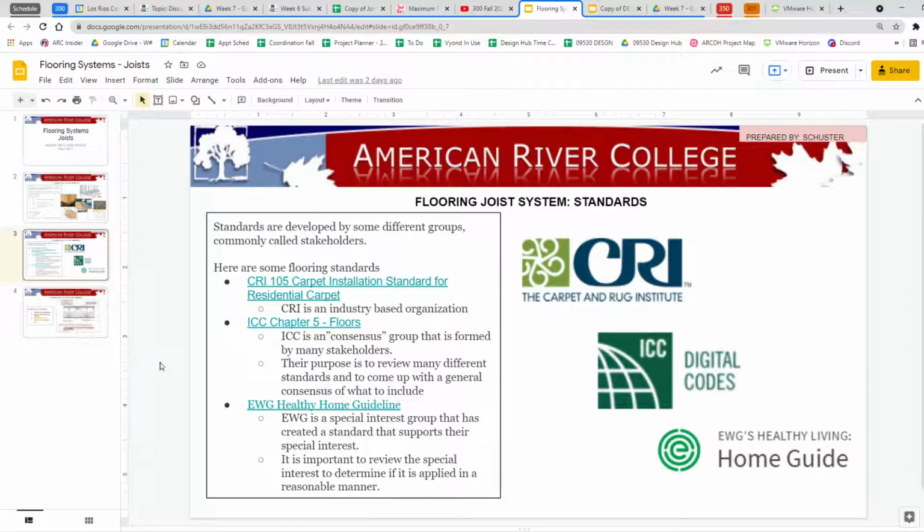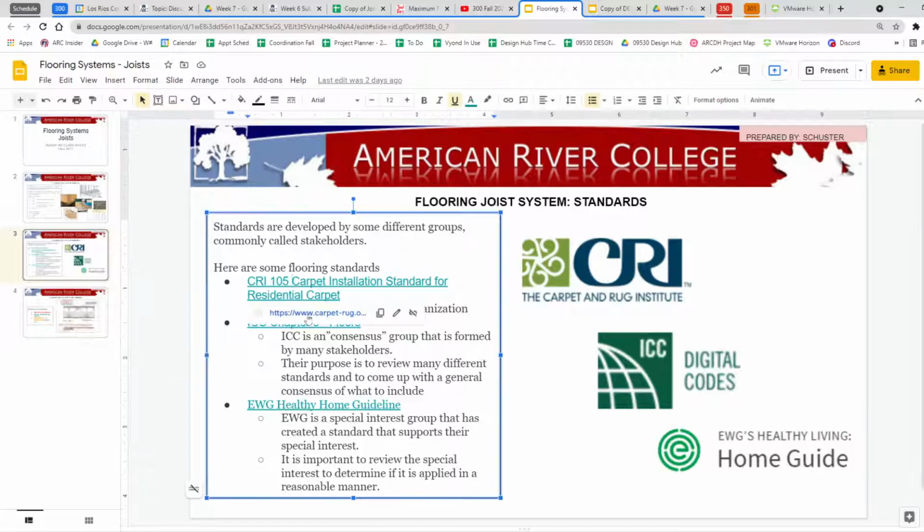Okay, for residential carpet. And that's all they have to say. They don't have to say that you have to make sure the floor is bare and clean, and there's no warp and no nails sticking up, and the wood has a minimum number of knots, and then you have to put an adhesive down and a vapor barrier, and then a cushion of this size. You just say, follow these standards, and you're done. And then it's up to the contractor to know the standard and look it up. So these are really nice, and we'll take a look at this one.